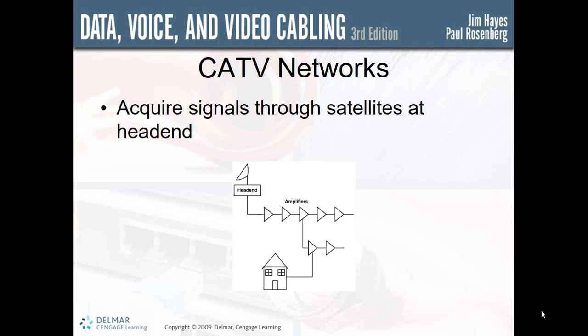Your VCR has a modulator built into it, because videotape cannot record the very high frequencies used in broadcasting. So in the previous example, the station used 216 MHz. The VCR must record at frequencies that are too low for a television tuner to pick up. So when you play a videotape, the information from the tape is modulated to channel 3 or 4, which your TV can then display. Once we begin to customize television systems in the home or office, the modulator becomes a very important device. It's necessary to assign the various video inputs to specific channels so that a television can use them correctly.